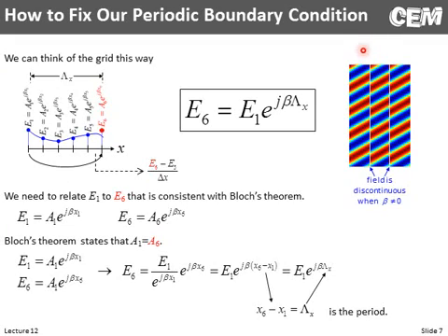So if we're using periodic boundary conditions, let's take the field in some unit cell. If it is periodic, I should be able to stack it onto itself and see nice continuous fields, and I don't. That's because our wave is coming in at an angle and we have these phase discontinuities. So we can't immediately apply the same boundary condition we talked about in the last slide, because the fields on the left side of an interface do not equal the fields on the right side of the interface. And why don't they? It's because of this phase term.